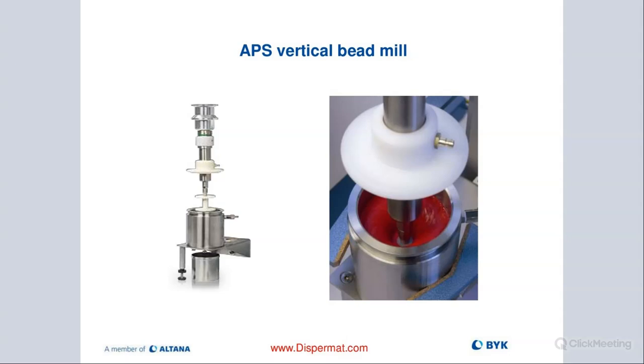And then when I'm completed with the milling process, I didn't mention that there is also a cover that you have to put on during the milling process. There's a clamping ring that goes around it to secure the cover. So we don't want to have product flying out of the container while we are milling. But once we complete the milling process, we can open up a drain plug on the bottom of our top vessel. There's a screen embedded in there.